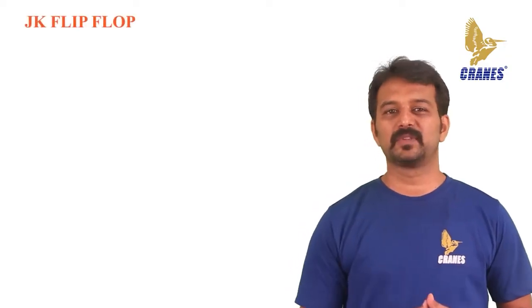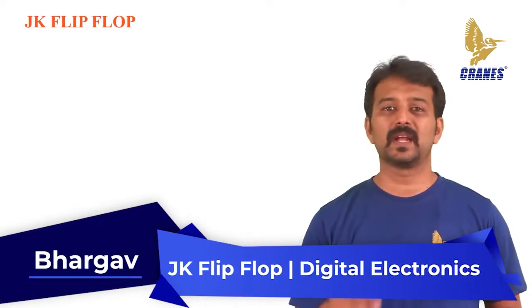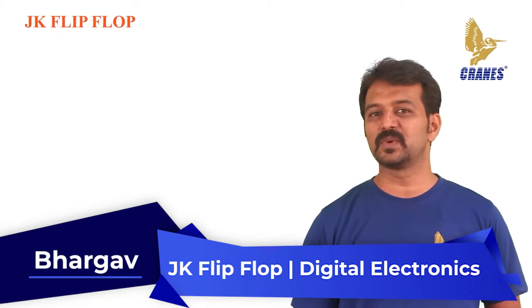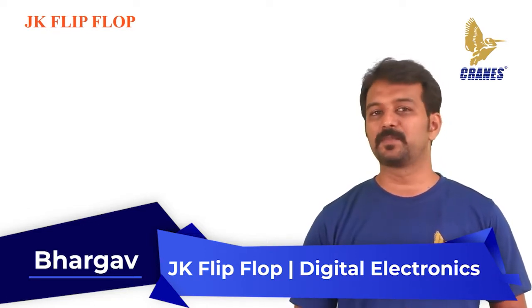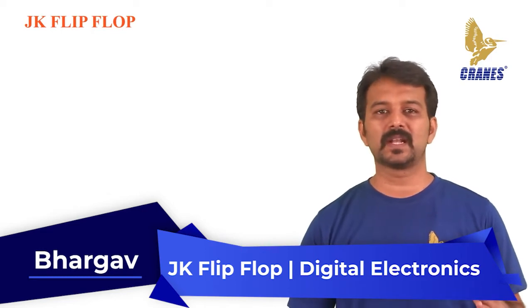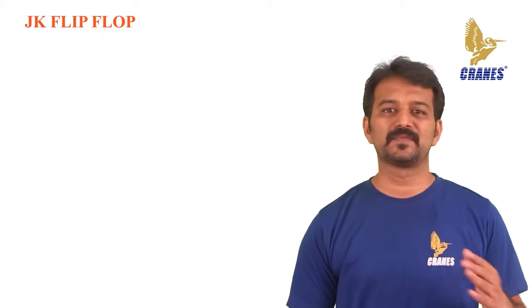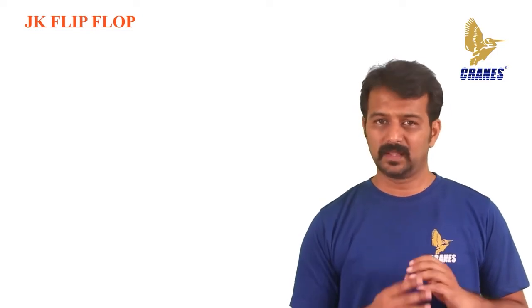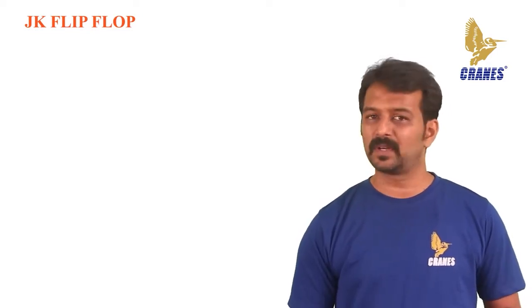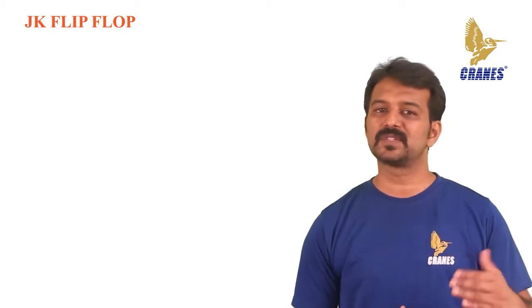Let's now discuss the JK flip-flop. The basic SR NAND flip-flop circuit has many advantages and is used in sequential logic circuits. But it suffers from two basic switching problems. The first problem is when set and reset are equal to 0, this condition should be avoided. The second is if set or reset change state while the enable input is high, the correct latching action might not occur. To overcome these two fundamental design problems with the SR flip-flop design, the JK flip-flop was developed.